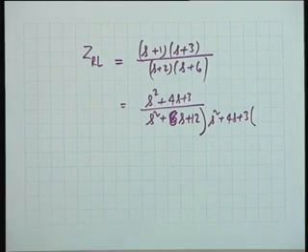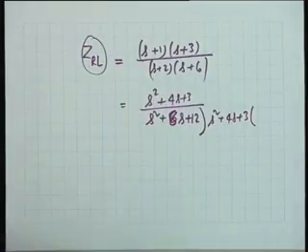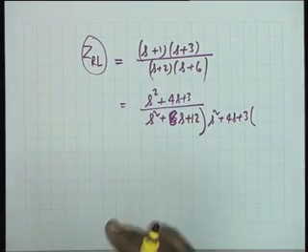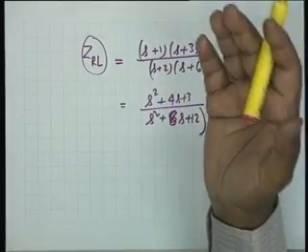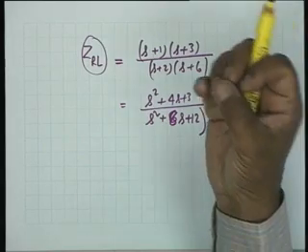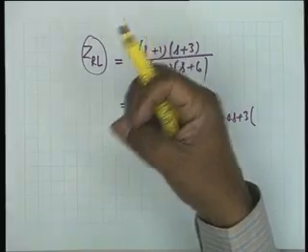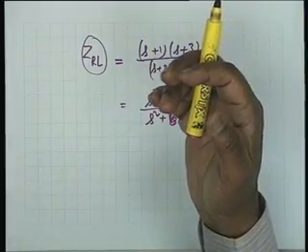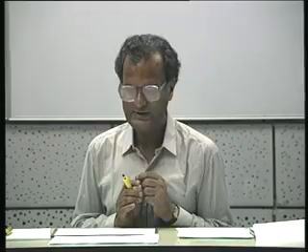Is the point clear? Similarly, if you want Cauer 2, can you start with ZRL? Yes, you can. That's right. You can start with ZRL. So, in Cauer 1 and Cauer 2, you have to be very careful. Similarly, Foster 1 and Foster 2, you will also have to be careful. Which one is to be divided by S? ZRL or YS. Okay. Without spending any further time on RC and RL, we'll take further problems in the problem session.